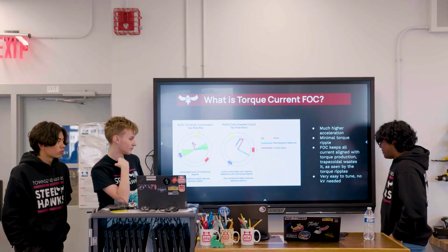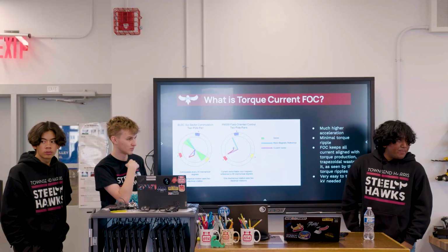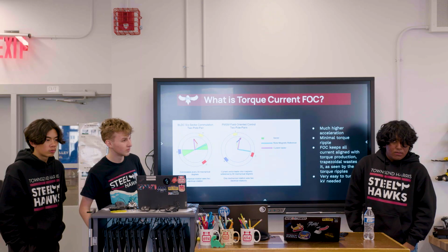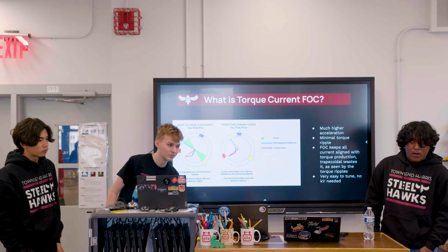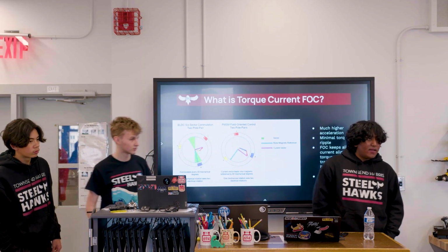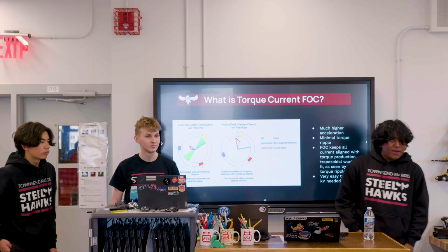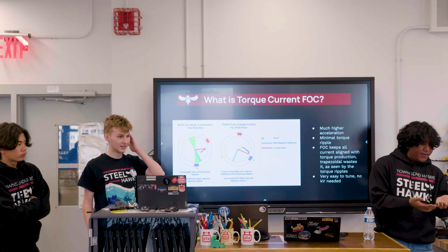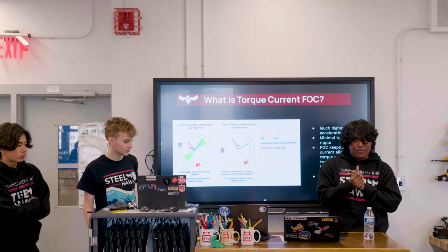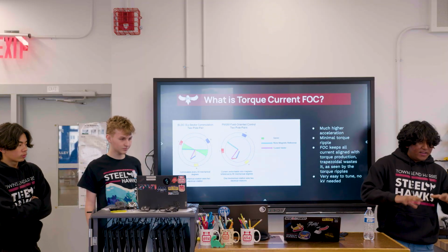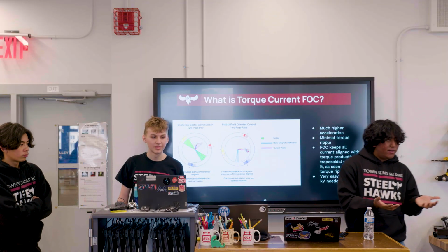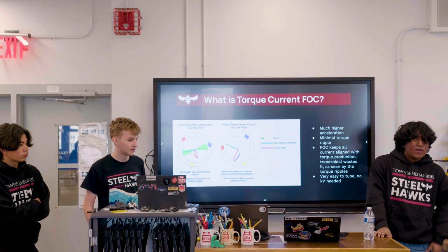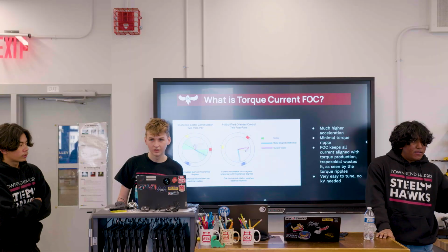Yes, yeah. Anything else? Before the season, you just decided we're using torque current on every motor. It's not a decision you're making depending on drivetrain versus this mechanism. It's a software issue. It's not a mechanical issue. Well, I guess it is a mechanical issue because you're forced to use CTRE devices. But we didn't change anything physically on the robot. We always used Falcons, and we just changed our code. That's it. So it's already built into your motor, just behind the CTRE paywall.